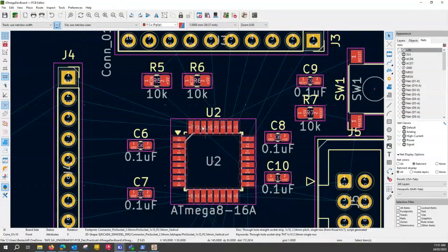So if they're crossing here, that means that you really need to swap those pins. Normally with a lot of microprocessors, you can actually assign pins to be either RX or TX. With this one, you can't do that, which means that they're fixed. You keep them as they are. Alternatively, you could just wire this into any two general input-output pins, and then you can communicate using software. It's much better to use built-in RX-TX functionality, so we're going to do that.